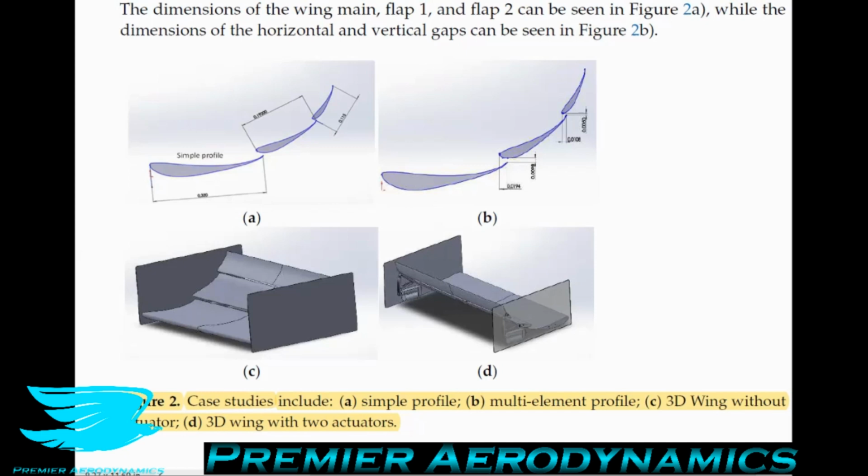So it's very sharp. And again, if you were to put even this airfoil in a free stream flow, and the angle of attack was actually 28 degrees, it would definitely separate the flow. And then the third element, which is 60 to 65 degrees, that's even worse. But because they're all working in unison, the flow coming from one airfoil hits the second airfoil, and it's redirected so that the effective angle of attack is actually much lower than 28 degrees or 60 degrees. So the downstream airfoil can handle it.